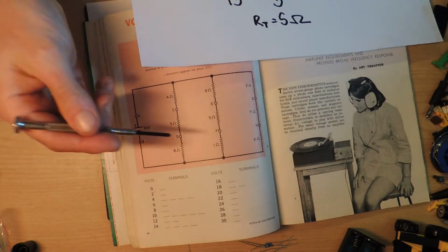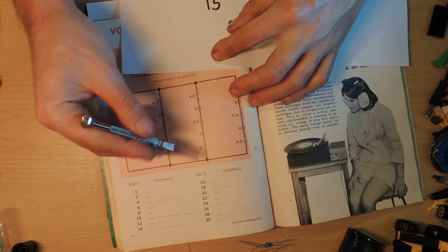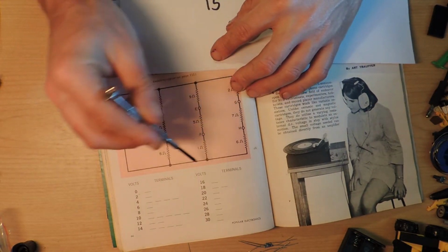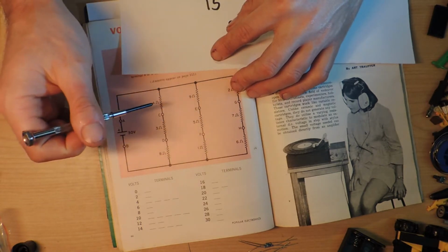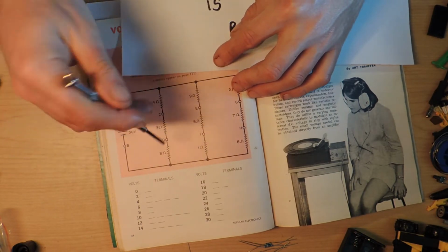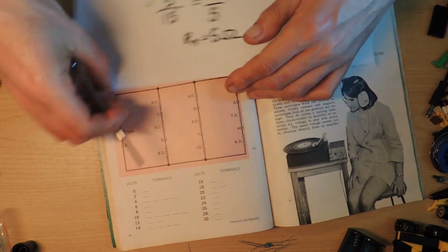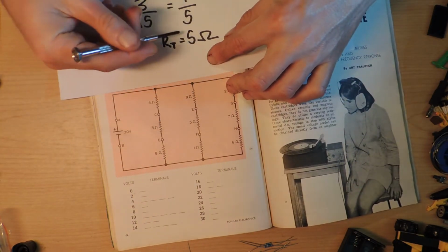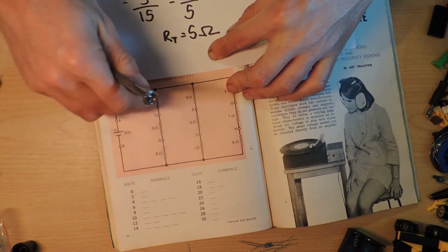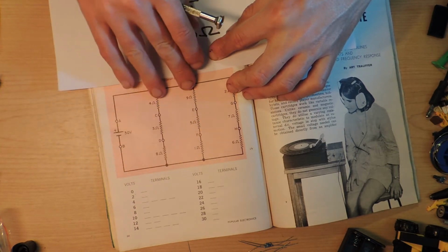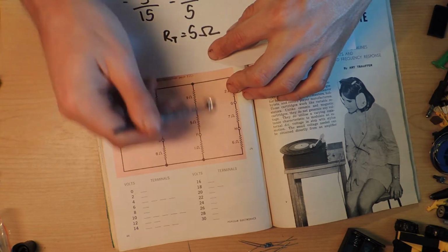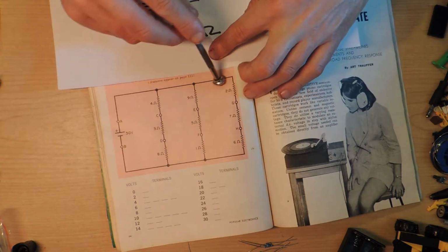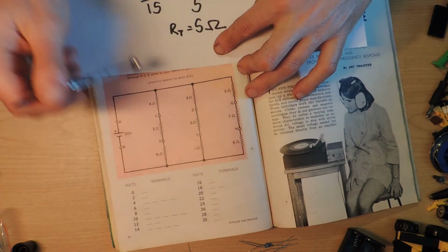If you've got 15 to go through here, 15 to go here, and 15 to go through here, but you've got 3 different paths to go through, it's going to be 1/3 the resistance. If that kind of does make sense. But it's definitely a lot lower than going just through one path, right? If it's 15 to go through here, but I can send my little troops down this one as well, I'm going to get twice as many troops through, and if I can send them down this one, I'm going to get 3 times as many troops through.